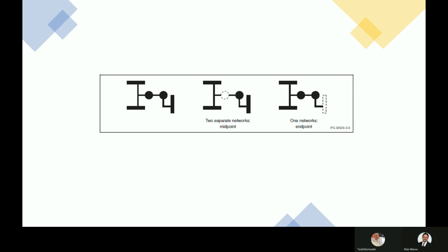Now, what's interesting with these nets is when you make these nets, the designers have a schematic diagram, and then they use layout software and they lay it out to the PCB. IPC specifies how you can assign the test points, because we know that they put some sort of solder resist on the outer edges of the board and a surface finish on the copper to keep it from contaminating.